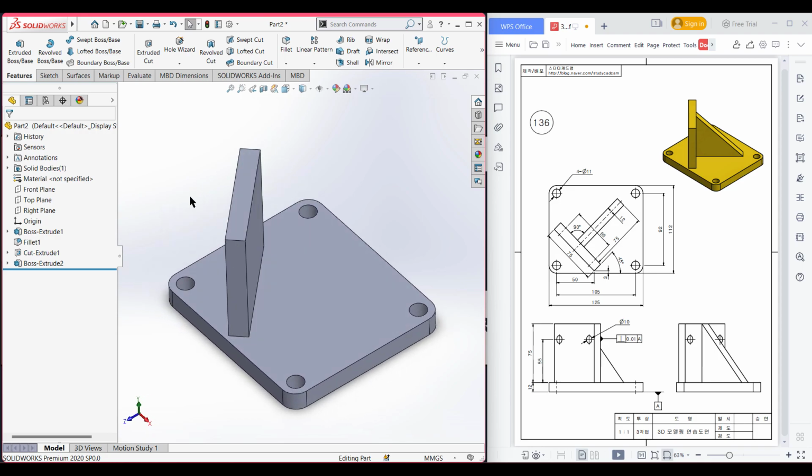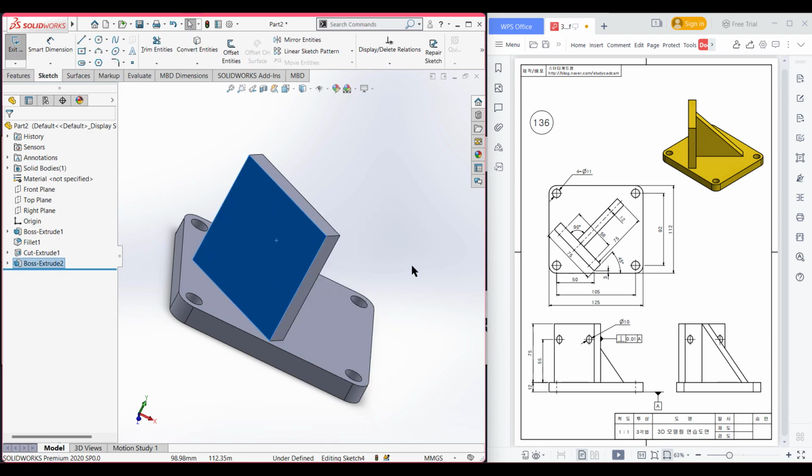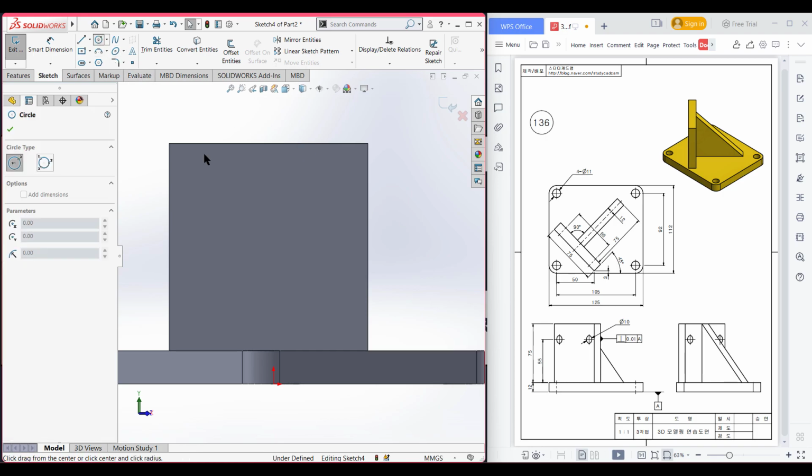So it's time for doing the extrude cut circle in this rectangular block. We can see this circular extrude cut has a diameter of 10 unit, and it has a vertical distance of 55 from this line, and a horizontal distance from this center point of 56 divided by 2 unit. So I am selecting this face. Now sketch, now normal to it for a better view. Now select a circle, place a circle here, and dimension the circle to 10 unit.